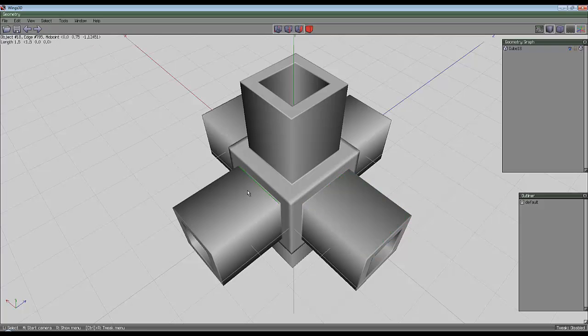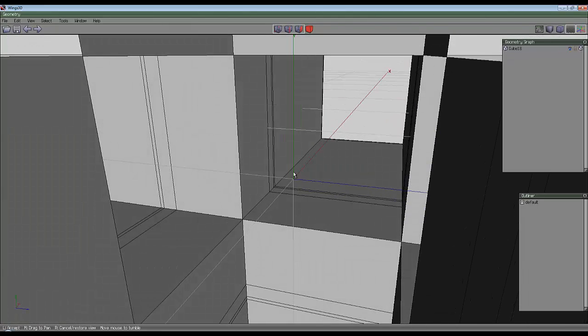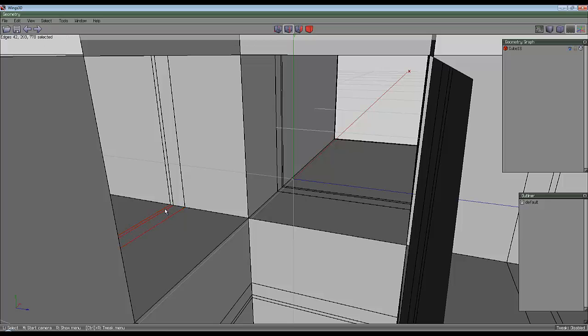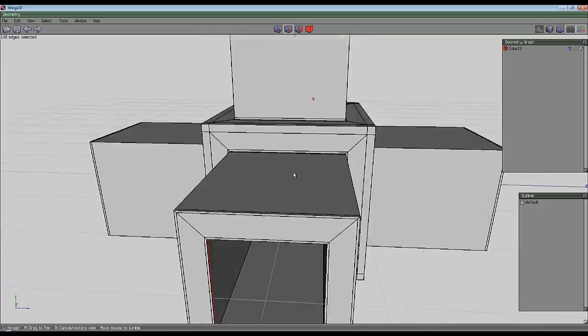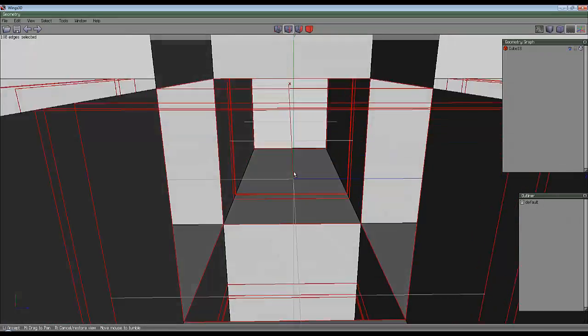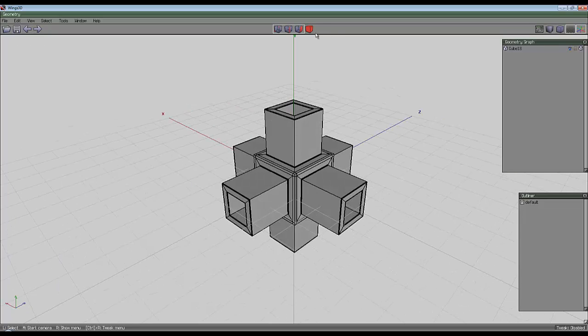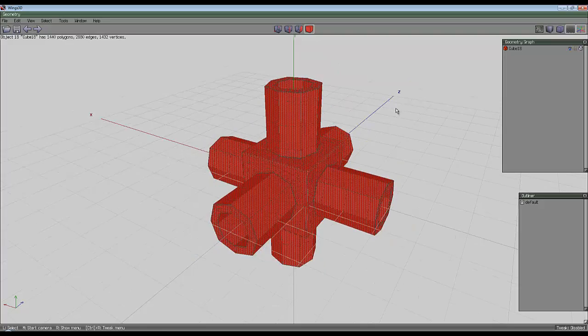It's going to need some sorting out here, but bear in mind these are going to be cylinders, and let's have a look inside. So we've got some additional geometry here that's probably extraneous, so we go I for identical, and we get loads of things selected. This could be a problem. So I could either try and get rid of those now or try and trim them off later on. So let's try taking them out later on. So I'll hit smooth once.